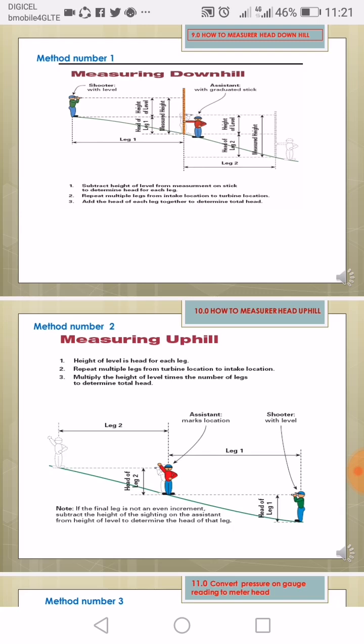Suppose you start in the picture. The green set becomes the one up where the red set was, and where we put the stick here. The man is on top and moves down, the red set comes down, and the green set becomes the one up where we put the stick and take the measurement. By repeating the same thing and measuring the total measured height, you subtract the height of the marking pin on the stick. Okay, I am just explaining this.